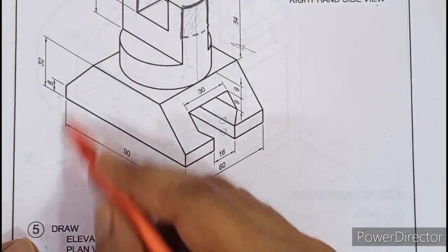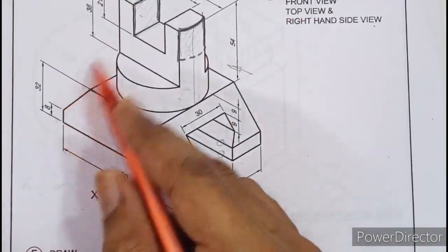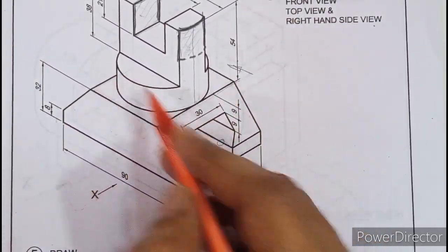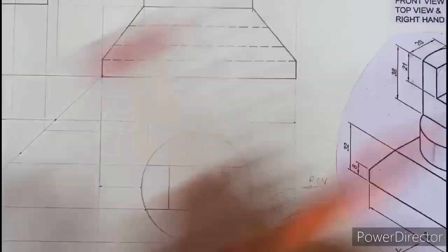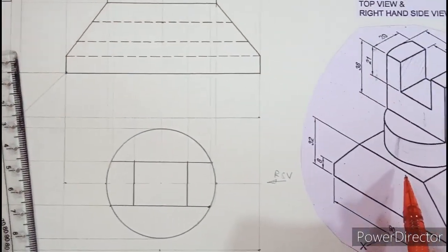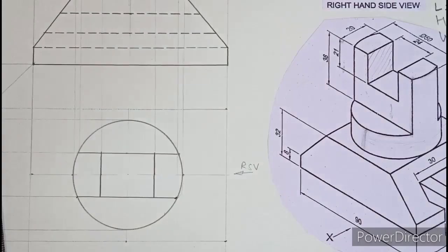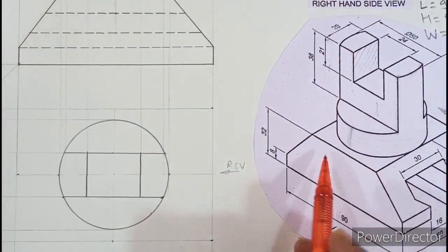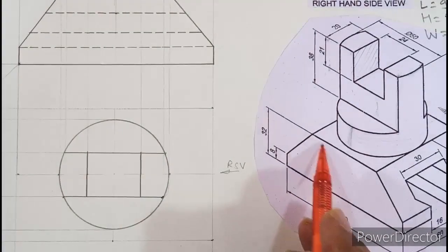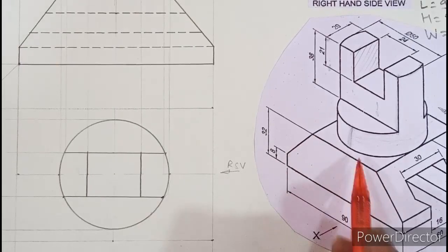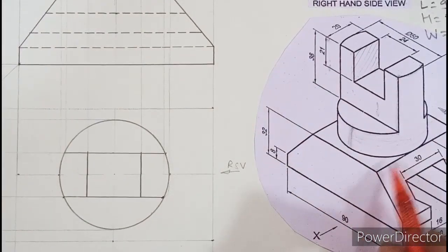So you have to look at the top view from this side. See, X is here, so you have to look at the top view from this side. These two lines will be the vertical lines which are 50 apart, and the rest is 60. So in this diagram, if you try to connect with this, let me shift a little. When you look at the front, you'll find this dimension as 60. Sorry, diameter 50. So in the top view, if you observe, this is 50 and the vertical is 60.